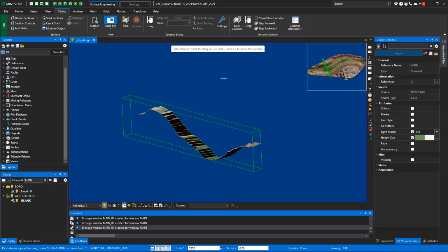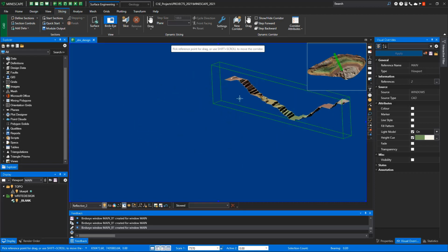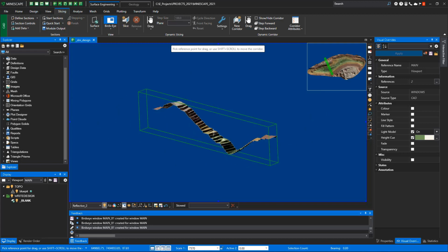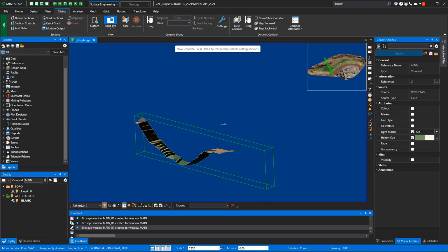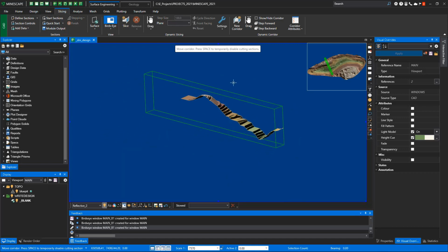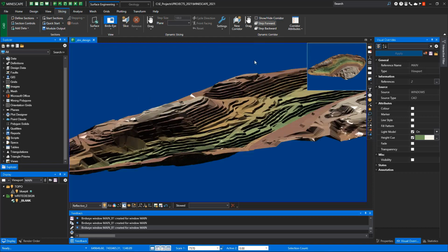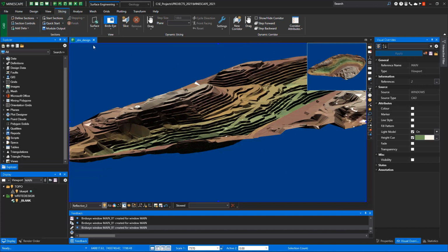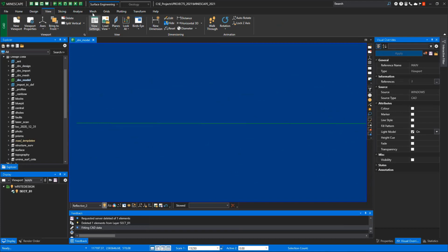The drag is pretty cool. So it says pick reference point or use the shift scroll. So if I just use the shift and scroll wheel, it just scrolls right through there. Or I could just click on one. And if you notice how it's moving that plane now, up, down, whatever elements you have out here in your CAD, it's going to slice. You're done with it, you just hit show or hide the corridor. So if you're done with that window, all you have to do is just toggle it off. It's all good.